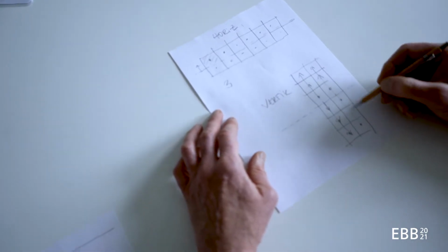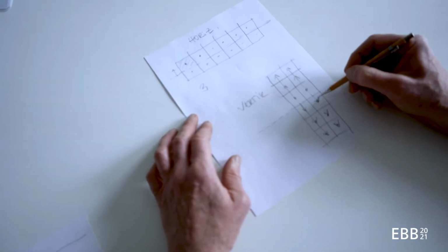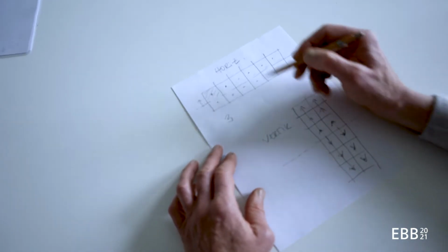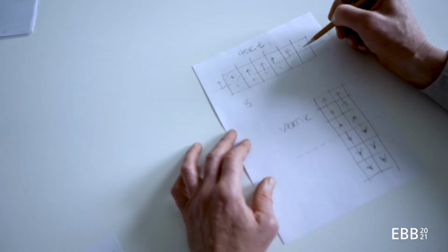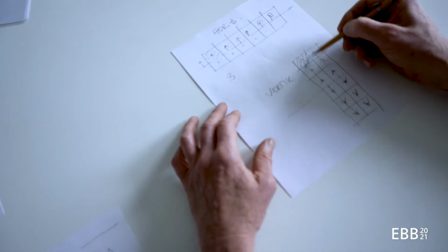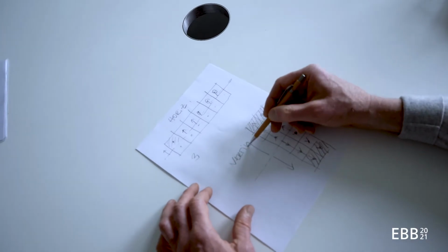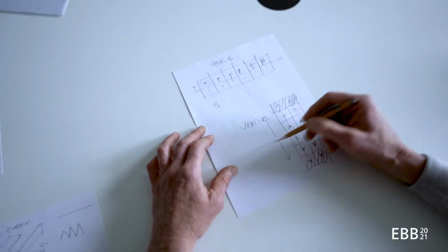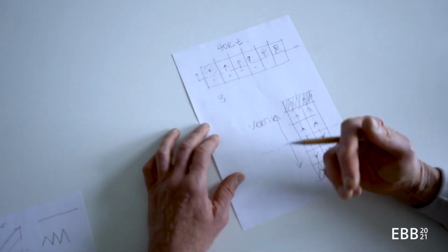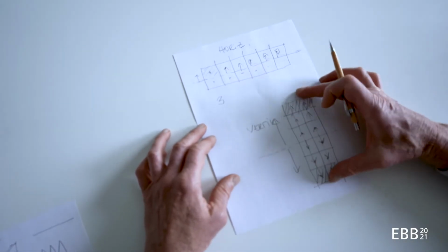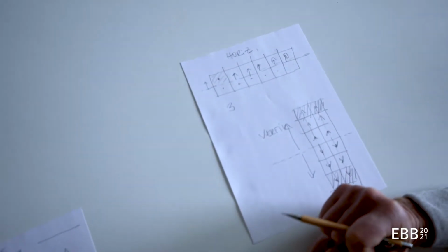and the same for the lower part of the section. So if I add up these lever arms, the sum is much bigger than the sum of these little lever arms here all together. And this is why a section that I put in a position which is far away from the neutral zone in the middle is much more efficient than if it's closer. But the disadvantage is that this here is much higher than the other one, so I need more space on the interior of my building.